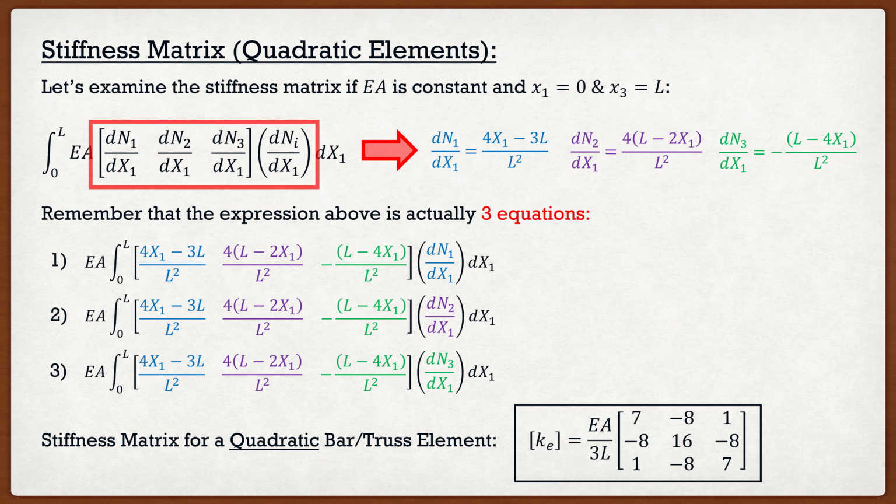So the question is, what are we getting if we switch from a linear to a quadratic element? Well, remember the approximation function for the elements. The nodal displacements will always be the same whether you're doing a linear or a quadratic element. However, these quadratic elements include that additional node, and the approximation function used is a quadratic polynomial. Therefore, the accuracy between the nodes will be much better than a linear element. But of course, the quadratic element has a larger stiffness matrix, therefore more computation time. So the question for you is, should I use a lot of linear elements or fewer quadratic elements? You want to try and find a nice balance between the accuracy of the solution and computational expense.